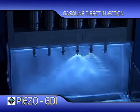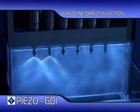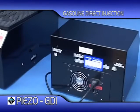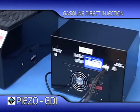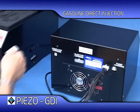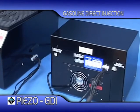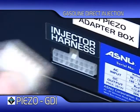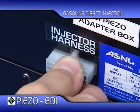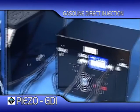As other manufactured piezo injectors are introduced to the automotive market, ASNU will of course produce flow rails and harnesses to suit them. This short clip shows how to connect the ASNU Piezo injector box to the ASNU Classic GDI system. First, connect the ASNU 605 adapter lead to the adapter box and then to the harness connector socket on the Classic GDI machine. Now, attach the ASNU 604 injector harness to the harness connector on the adapter box. You are now ready to test piezo injectors.